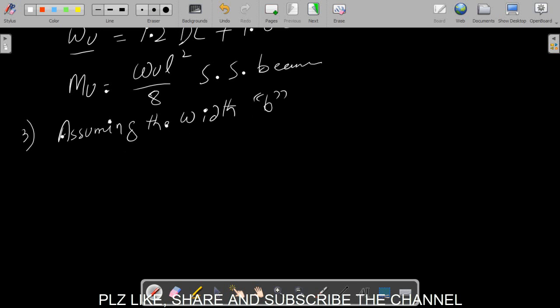We have to assume such a width of the beam that it does not cause any congestion of the reinforcement. Similarly, it can easily accommodate the bars, and it will not cause too much shear reinforcement, because the width of the beam also plays a role in shear reinforcement, right?